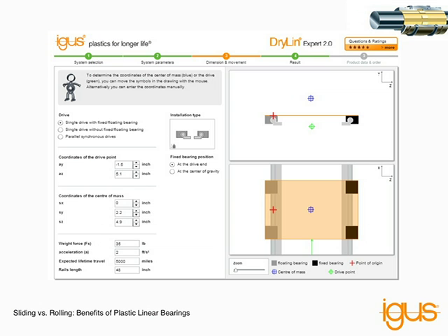One really critical function of this software is that you're able to tell the system where the center of gravity is for your application and where you intend on driving it. It's going to measure those coordinates from a preset zero point established in the software, and after you put in your load, acceleration, and your expected lifetime travel, you're able to take the next step. So this is a real clear way to see it on the modeling software itself.